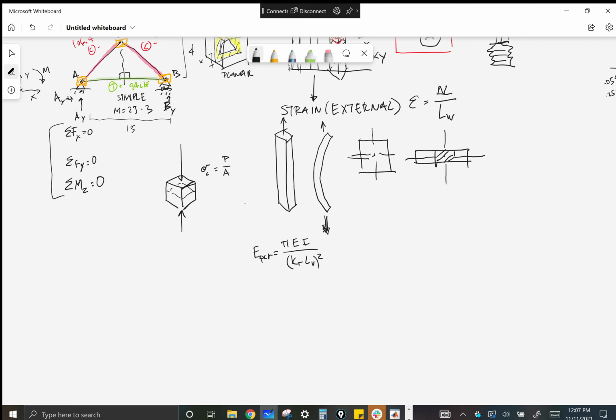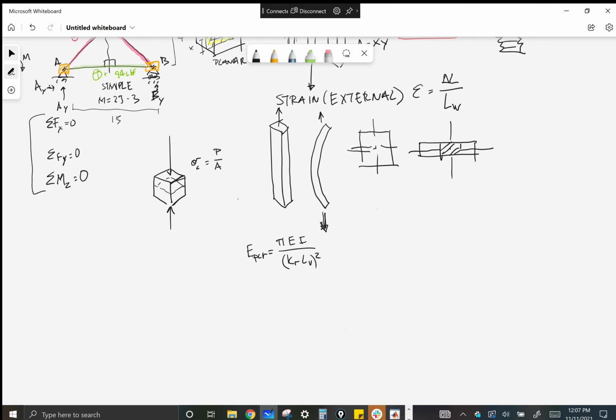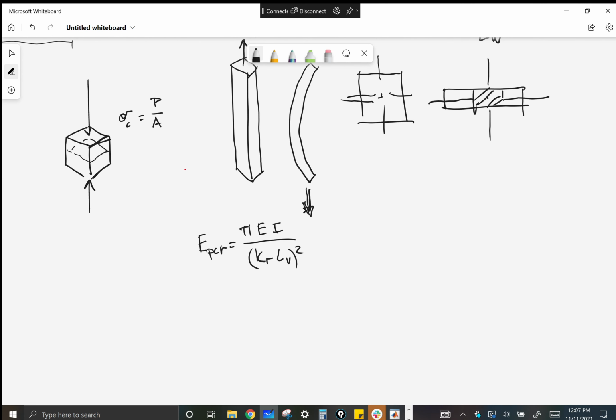You guys get that basic idea with moment of inertia? You could answer a question about it, however it's worded. Okay, and then other things you might come up with questions on is simply saying things like, if the end condition is larger, is the failure load higher or lower? Just understanding where length has a huge effect. Squared. Is it longer or shorter? Does it make things stronger or weaker? Yeah.